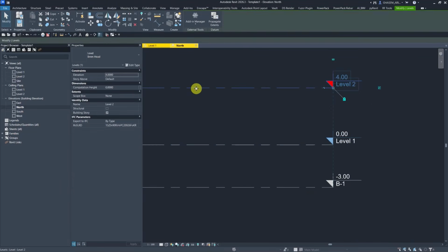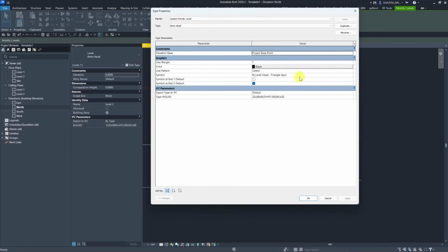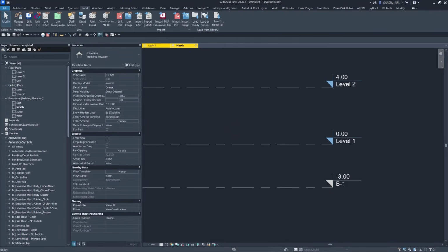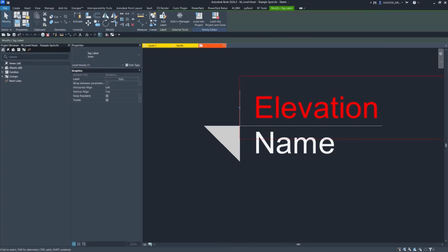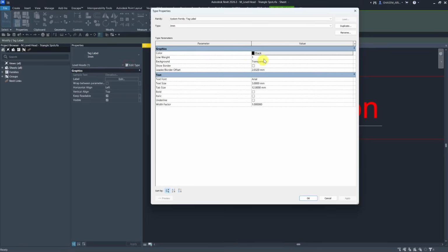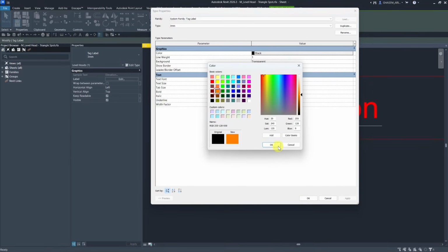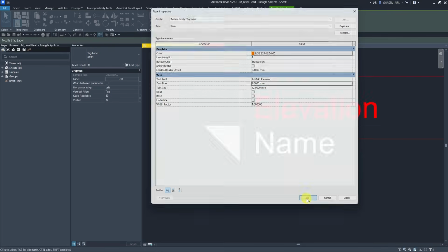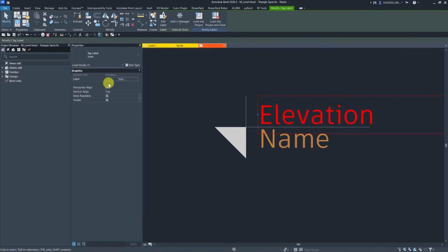Okay, here we go, guys. Now, I'm going to open up edit type again, get a copy of the name, search for it in project browser, right click and edit. And then here, we can basically just modify our symbol. The modifications could be applied on the frame, for example, the font size, the font type, and basically any other aspects that we might find necessary. For example, I'm going to activate wrap for both of the items here.